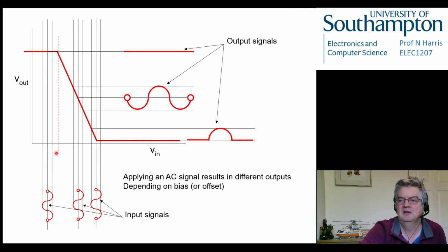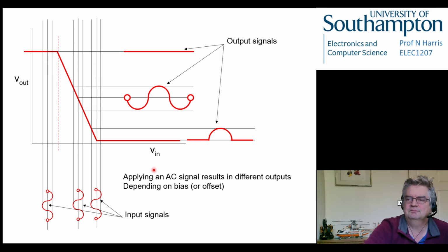That's an amplifier. If we go too high, we operate in this region here, where this bit will cause some amplification, so any signal going into this bit of the voltage curve will result in an amplification factor. But if it goes beyond that onto this flat line, we don't get anything, so we get this sort of half amplification at that point, and if we go further up we'll just get nothing out. So we obviously need to make sure that our input signal is coming in so that it sees this part of the curve. Okay, and this is called bias.